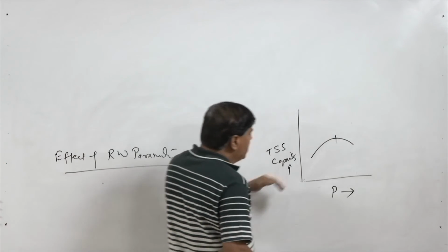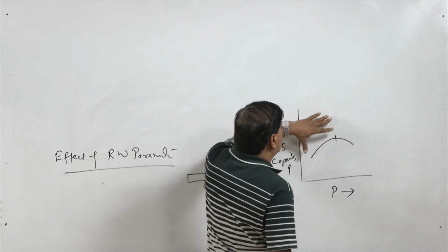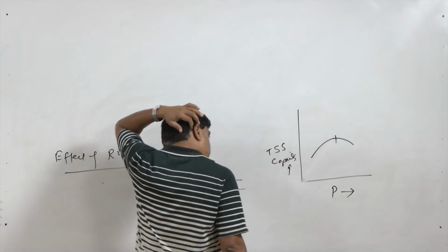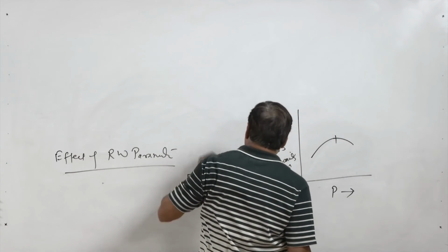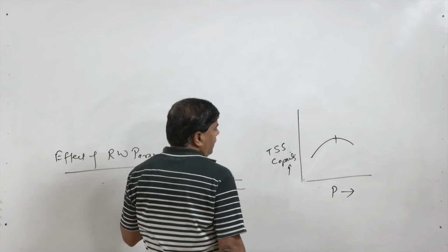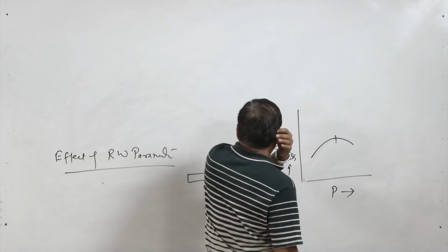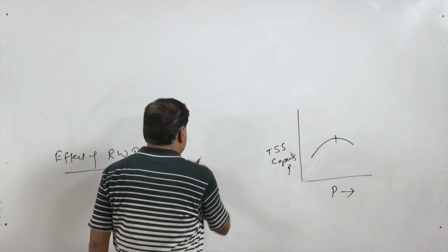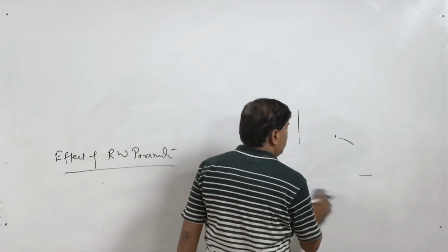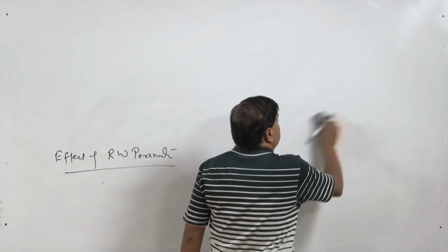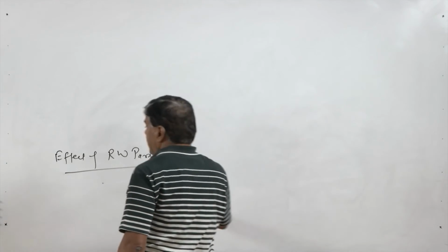But we need to have reasonably good pressure to avoid sparking. The use of too high pressure will reduce the contact resistance, but a little marginal increase in pressure helps in effective consolidation as well as the solidification of the metal at the interface.